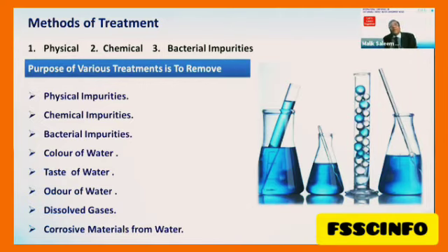Like in a textile, you will have to see for the dyeing, finishing, bleaching, what type of water is required. Normally, high pressure boilers having 80 bar pressure require conductivity less than 0.01 microsiemens per centimeter. We have to achieve that target by employing equipment based on the type of available source.